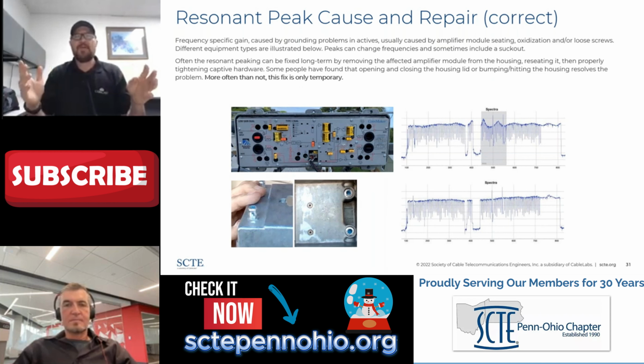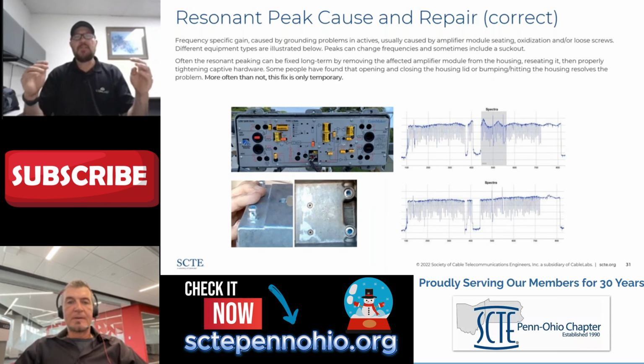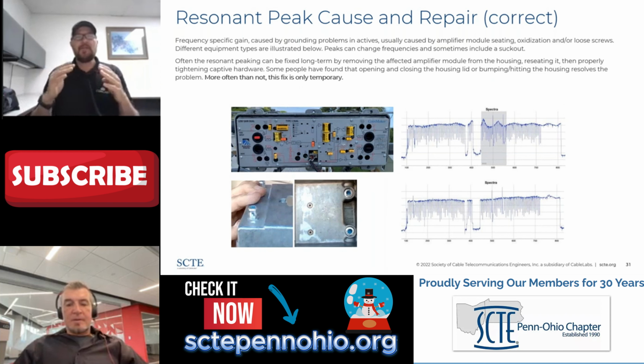So we see different amplifier types out there. This one happens to be the Cisco GainMaker platform, which has a very rectangular shape, and the placement of the module retainer screws inside of the housing, the presence of corrosion, and the different types of connectors that are used to interface between the RF module and the housing, in this case the lugs, can actually start to develop patterns in their resonant peaks. So amplifier modules like this GainMaker may have a very specific resonant peak signature.